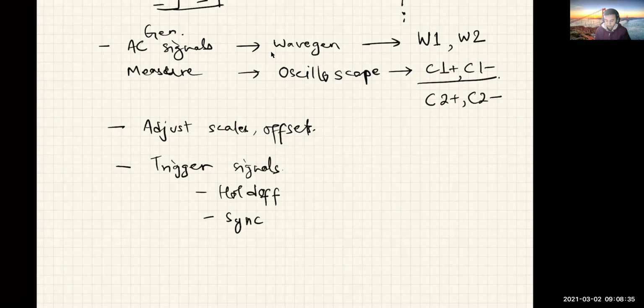Okay, so first of all, triggering is the idea of instructing the oscilloscope to refresh the image every so often so that the signal that's resolved on the display is humanly viewable.